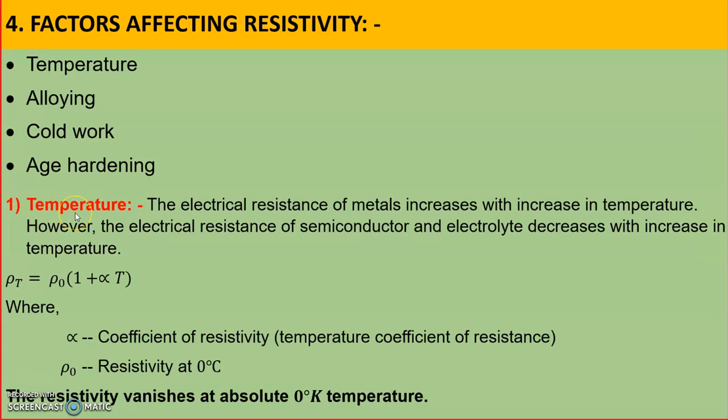So temperature effect you have studied. Electrical resistance of metal increases with increase in temperature. Remember this, because for insulator exactly it happens the reverse way. For metal, if you increase temperature, resistance will increase. But for insulating material, temperature will damage the quality of the insulating material. Means resistance of insulating material decreases with increase in temperature. So such questions are important for oral exam.